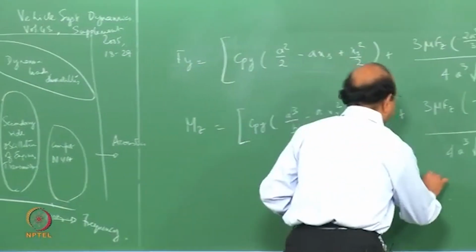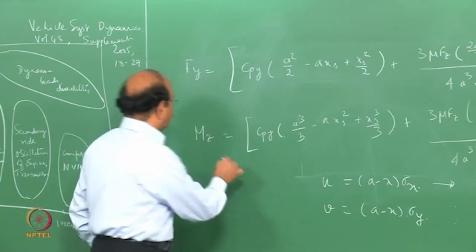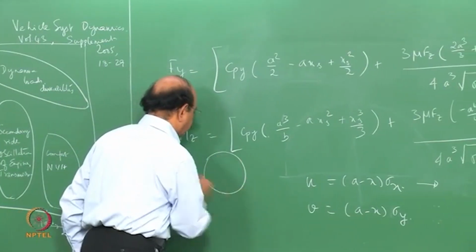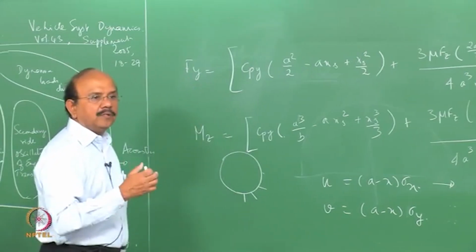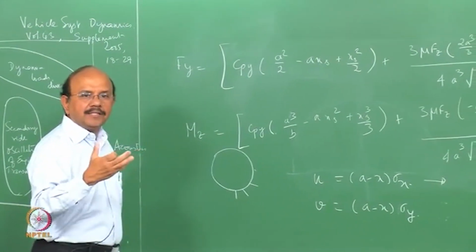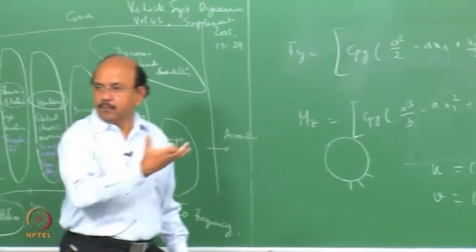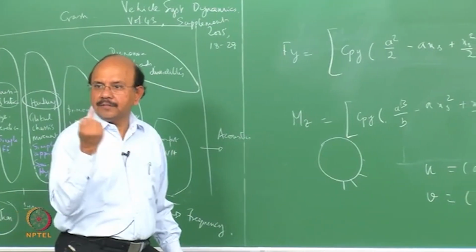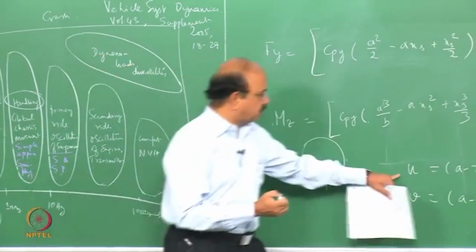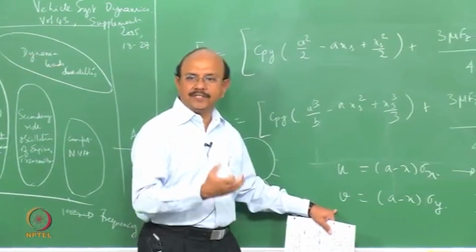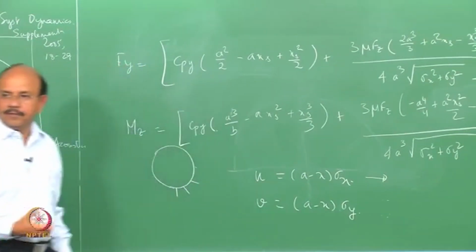In other words, these are the displacements of the brush. Remember that we looked at the brush, okay? In the brush model, we had those brushes. So now, please understand that there is going to be a longitudinal as well as a lateral force, both acting. So the bristle will be displaced in the x direction as well as in the y direction. This is a displacement. Go back and look at it. This is what we did before.